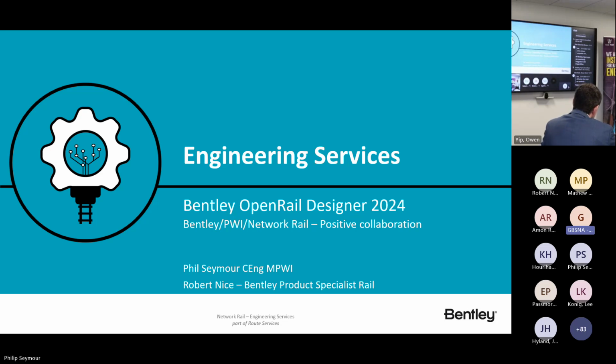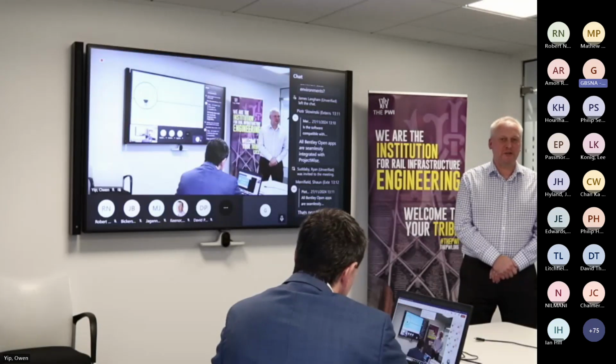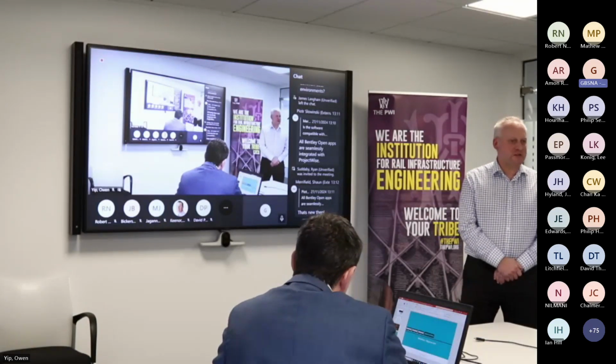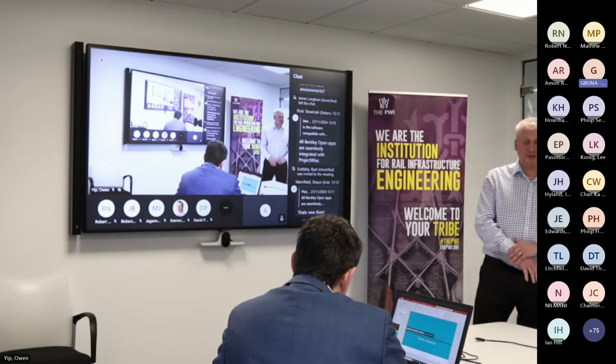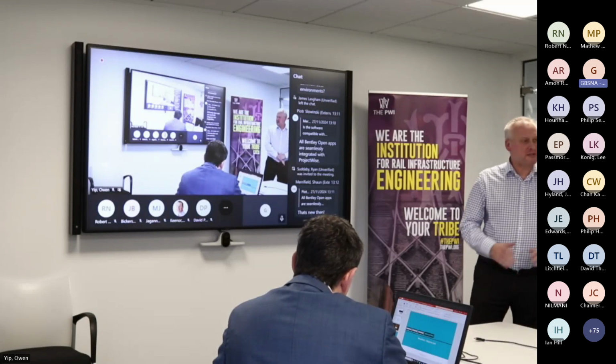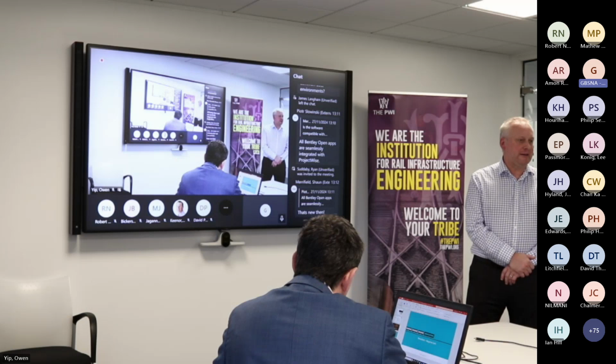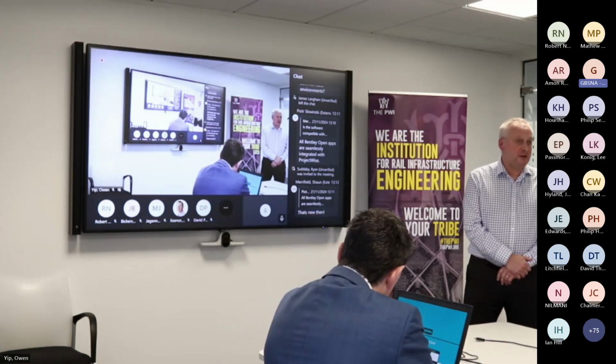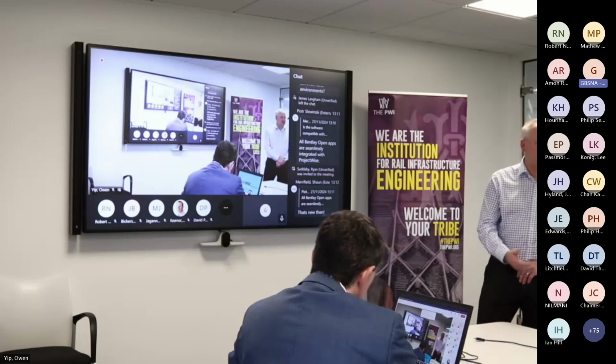As part of the Devon and Cornwall signal renewal works, we had to recover track points. The lead to the branch is an RT60 lead. I can't remember the switch size off the top of my head, but it's about 60 mil of negative cant on the lead. It's an interesting design. The alignment has a linear straight, which also has cant on it, and then it goes through transitions.